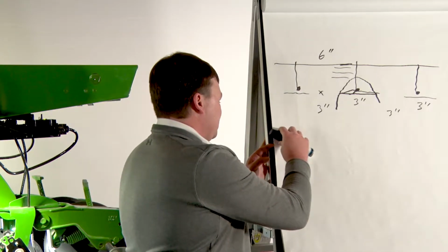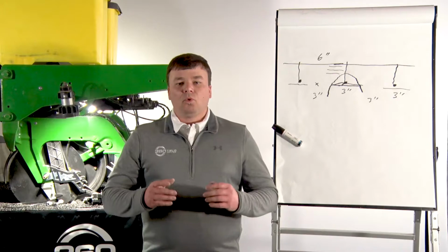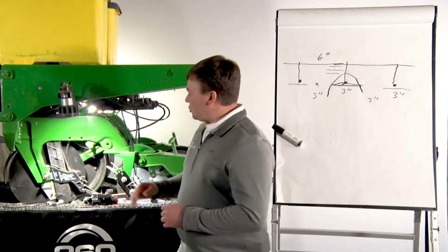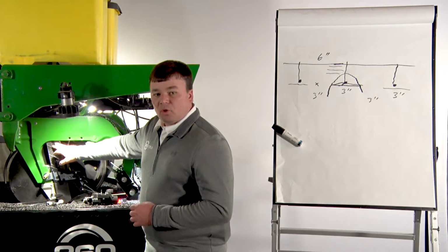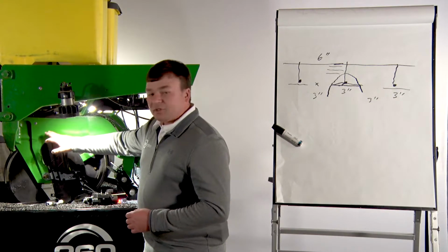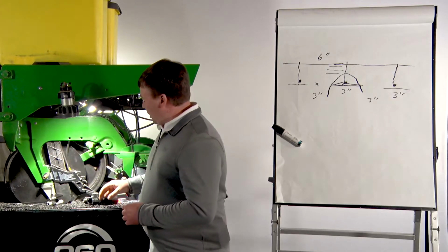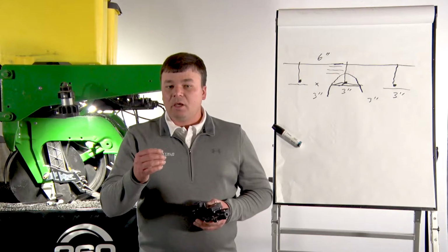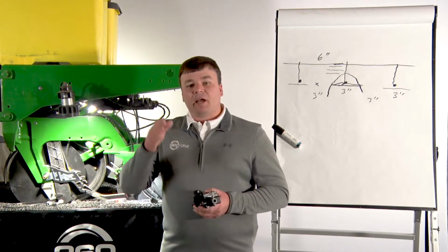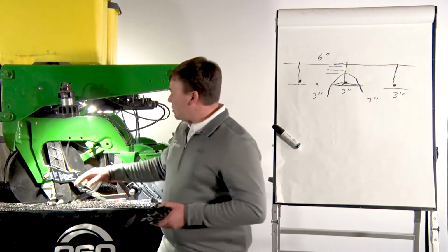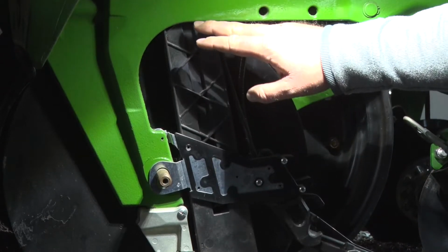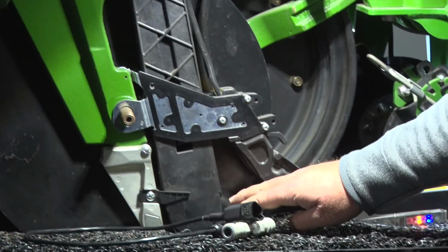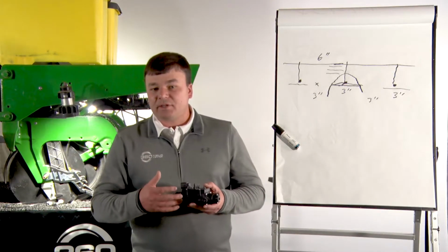I mentioned with 360 Dash, it gives you more control. We're using 360 Dash on high-speed planters, and the whole system starts here in the SpeedTube or the ExactEmerge system with the seed sensor itself. And we're picking up the fact that that seed is coming. And then from there, it's all based on timing and your planter speed. And we start counting the milliseconds that we know it takes from the seed to go from the seed sensor itself to its home position where it lands in the seed trench.